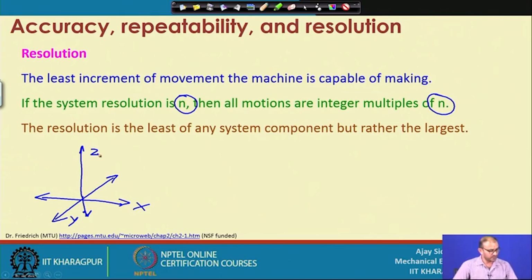Here we are using different motors: linear motors, servo motors and stepper motors are available. Let us talk about x and y only right now, because x and y are mostly located on the table, and the z axis is obviously the spindle axis mounted on the vertical side.